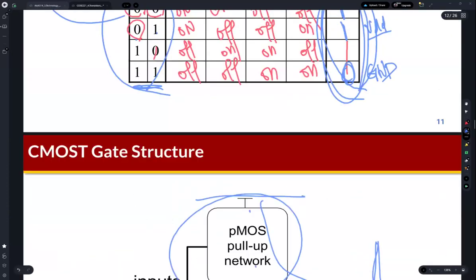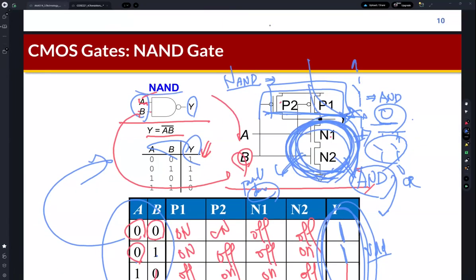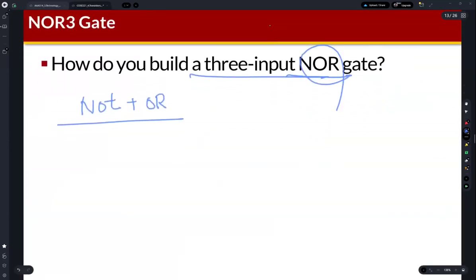So in the previous example, this is the NAND gate, with serially connected MOS transistors. I mentioned that this is the AND: if this is activated, then Y becomes 0. So it's NAND. With the same approach, this is NOR. Then how can we build a CMOS circuit?